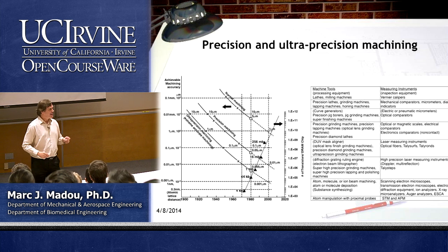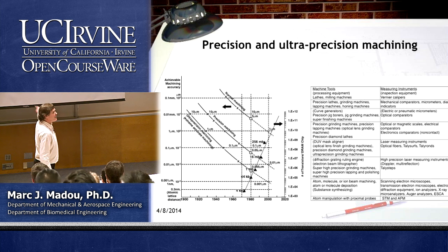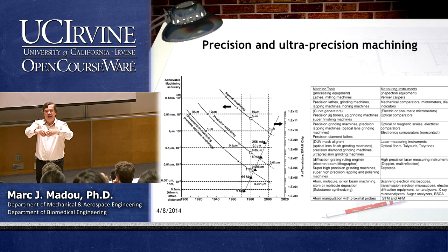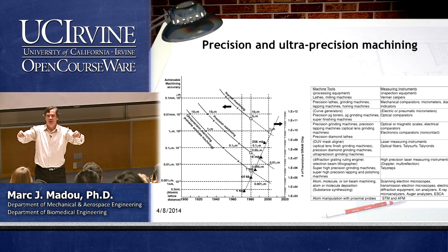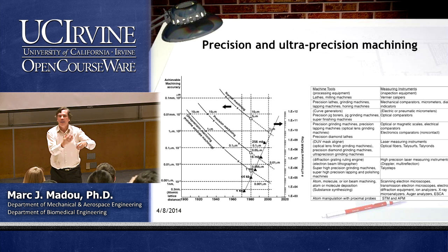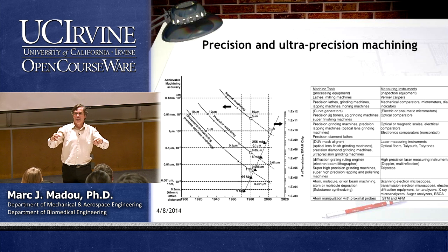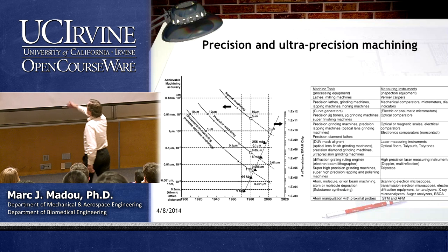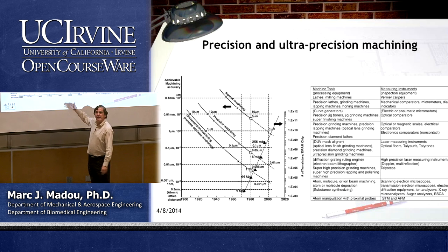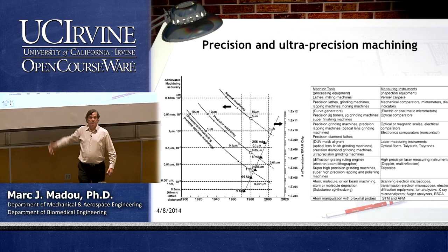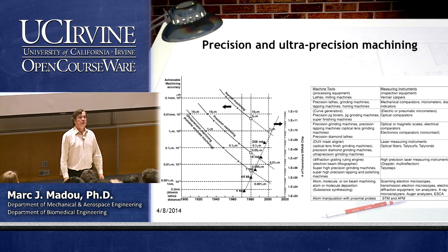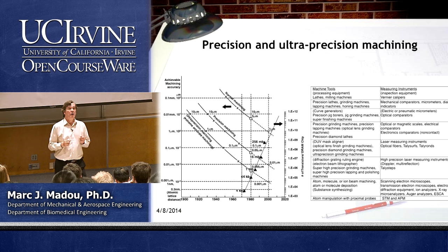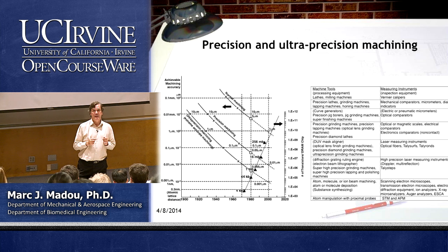You remember now, right? And actually, I kind of highlighted it by saying, look, in the beginning, 1977, it was kind of like a poor XY position stage, right? There was no feedback. They kept on improving that and improving it. They made it vibration-free. And they got improvement both in mechanical machining and in electronic lithography, right? So the key, binding this, is how good an XY position stage you can make.